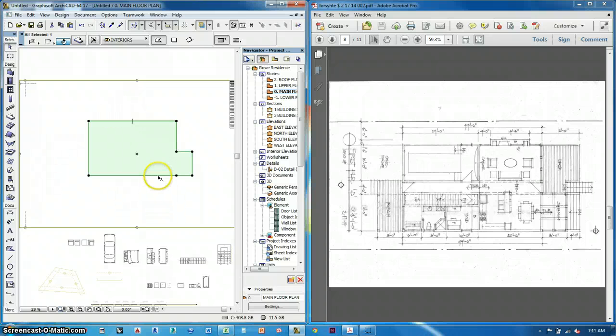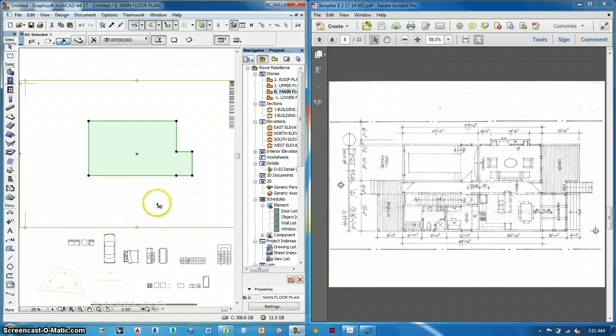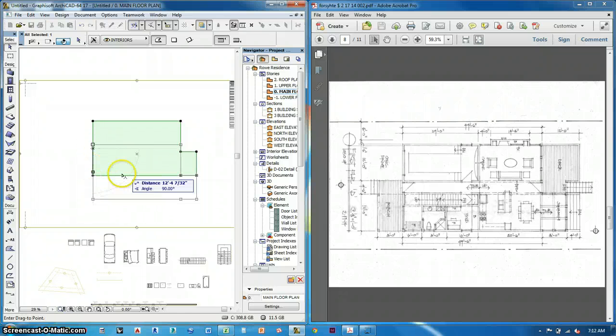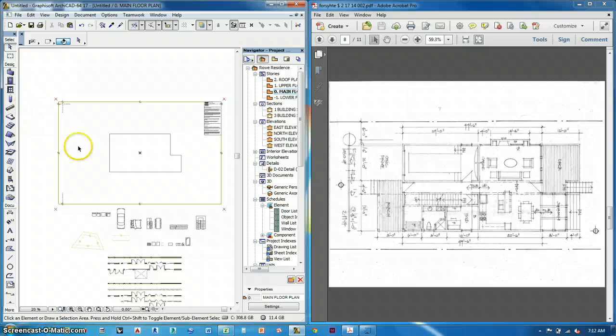So then if I hover over this side, I'll get a midpoint there. So I'm going to press Control D, hover over, click on that midpoint, and align it, holding down the shift key, and align it to that point. I'm going to drag again from that, and there I'm centered. So now I'm going to do walls. That's my slab, that's it.